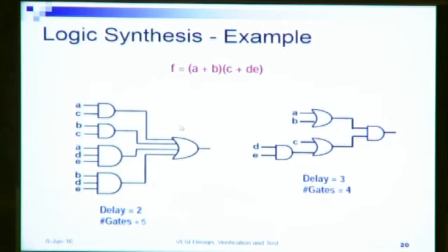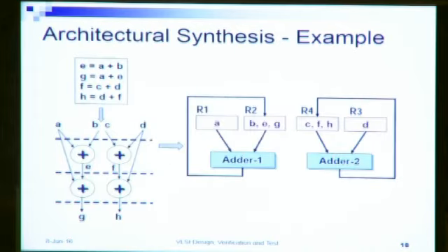We can also do such optimizations at the architectural level, and such optimizations will therefore be called the macro level optimizations of the circuit. For example, if we take this example, we said that for this realization we require 2 adders. We could easily have done a serialization and done this whole thing using 1 adder in 4 time steps. So if we had just 1 adder, we could do the same thing in 4 time steps.